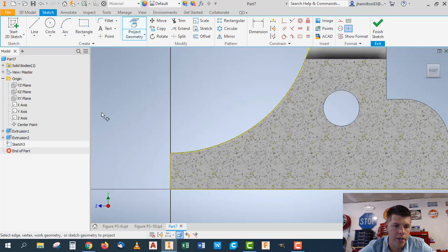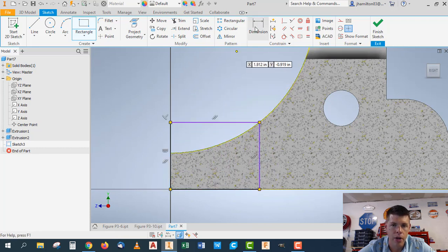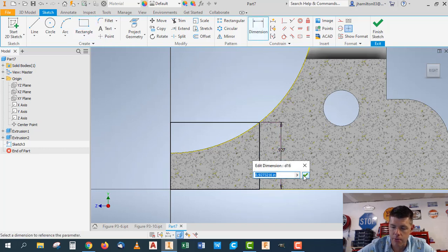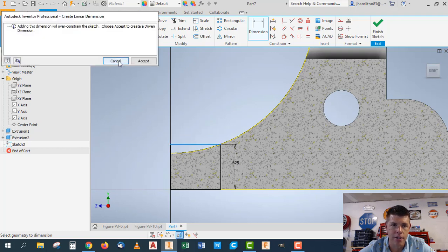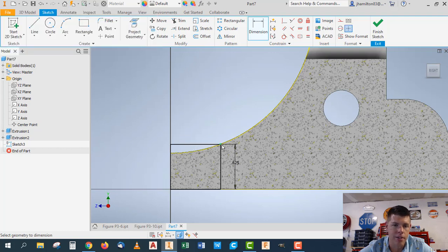We're going to draw in a rectangle. So I'm going to go to this corner and then just draw it anchored to this curve, like that. So what I'm going to do is dimension the height of this line now from the inside of the part. I want that to be 0.625, and it's fully constrained. So you can see that the size of this projected curve and the location of that endpoint control the depth of the cut, right?